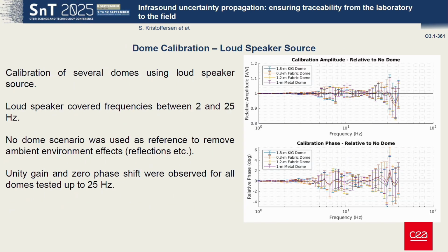And so now into some of this calibration. I did two calibration experiments. One used a loudspeaker source. It was in a wooden baffle that gave sufficient back pressure area for it to generate an infrasound signal down to a few hertz. It was reasonably pure, especially when we got up into higher frequencies, around 10, 15 hertz.